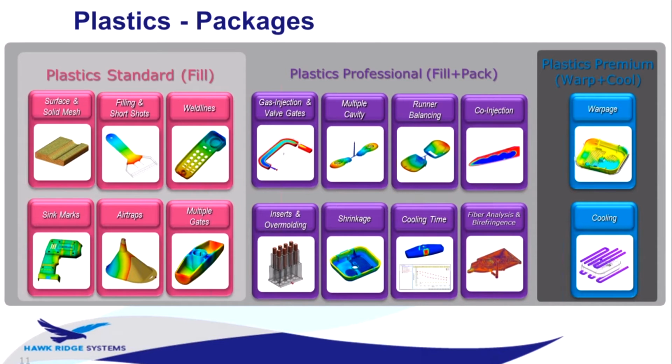Plastics Professional, we're aiming a little more at someone that has a little more control over the tool layout, the tool design, and the molding processes. We're going to analyze the fill and the pack process, and we can get to multi-cavity layouts. That means several instances of a part in a tool, or maybe a family tool with different types of parts laid out into a tool.